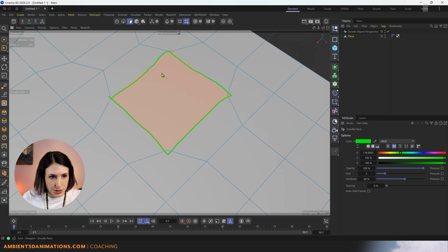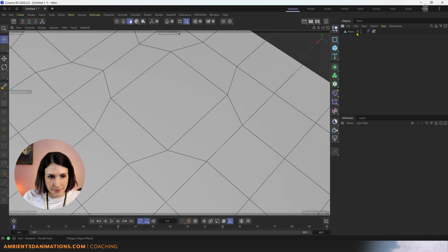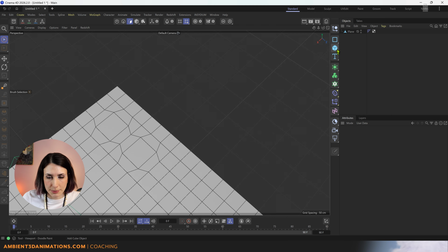And you can see it's orange, so that's the exterior of the polygon. Now the normal direction is perpendicular to that surface, so it is pointing outwards. So that's the axis in which we are going to be scaling around. So the normal axis is the axis we are scaling around. Like think of a tire and the axis on a tire. That tire or that wheel is rotating around that point there. So we're doing something similar here, except with scaling. We're scaling around that point. I'm going to delete this, and I'll show this further on a primitive that has multiple sides.